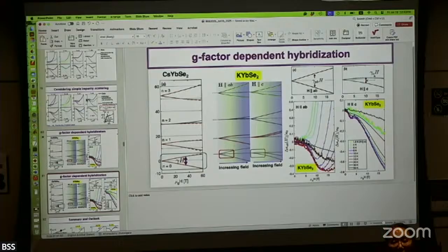When you have a setup, you have to be really careful about what paths can be possible. For example, when you go to higher temperature, say 200 Kelvin, and you have a very tight container, as I explained, the radiation heat is a lot. The radiation heat is deflected by the wall and shines again on your sample.